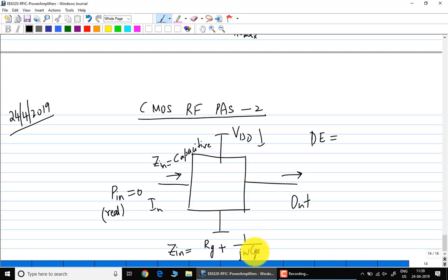I'll write it like this. Remember, how do you draw the transistor? All of you know, I think by now, from the gate, it has a polysilicon gate. Depending on the width of the transistor, you can draw the dimensions of the transistor. So let us say I have 2 or 3 fingers, you can have many fingers actually. I'll show the case with 2 fingers.